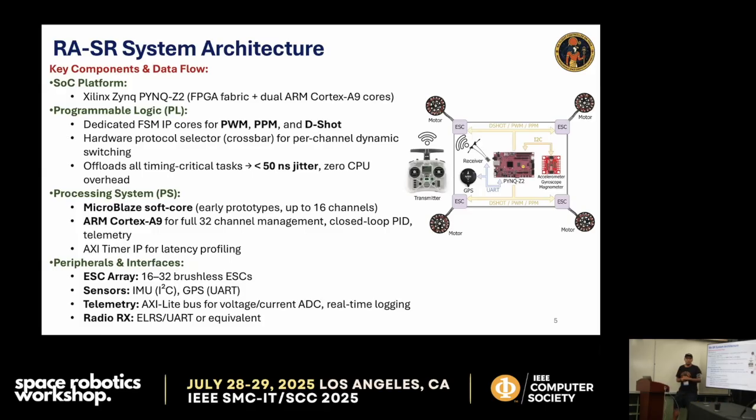Somebody will ask, why do you spend your time on a soft core processor? Because at the end of the day, it has its own job. I can replicate it many times and make multiple TMRs inside, and if something breaks, the rest will be doing the job. But the limitation came from the MicroBlaze, because it could only control up to 16 motors, as the cache inside that microcontroller is very small, but you can actually extend it if you have DRAM and other more sophisticated boards.